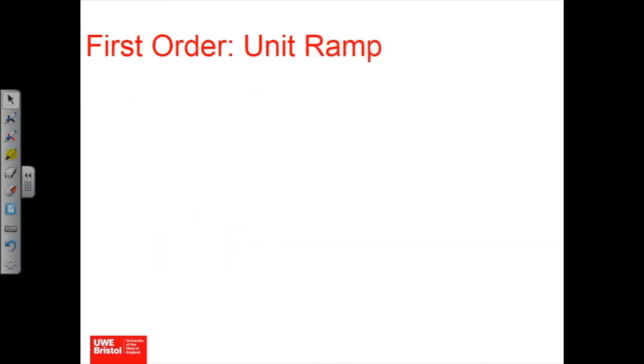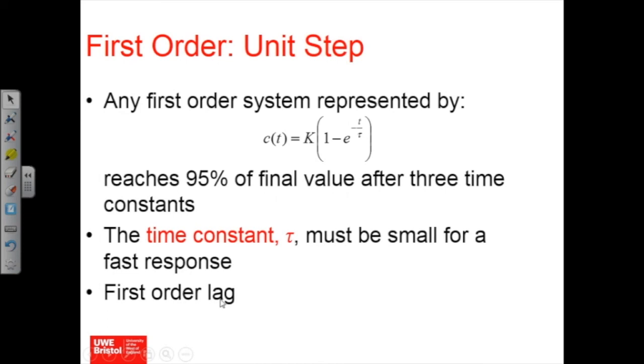Oh yeah, I'll introduce the word lag here. This system is known as a first order lag. And the reason for that is because the S terms are in the denominator. Most real systems exhibit lag behavior. Not everything, but most real systems do. Because generally speaking, the output from a system happens after the input's been applied, not before. We tend to turn that sort of thing on its head when we're looking at repetitive inputs like sinusoids.